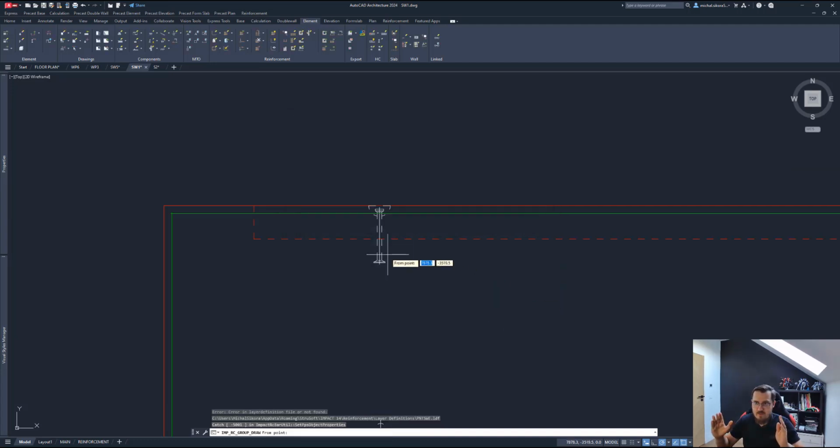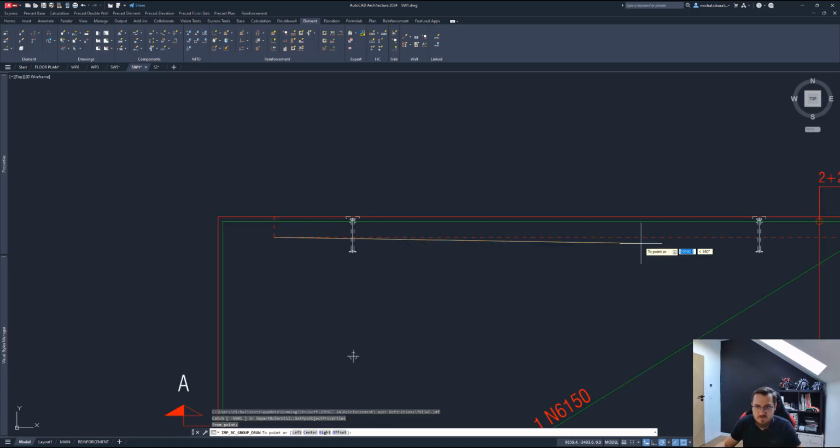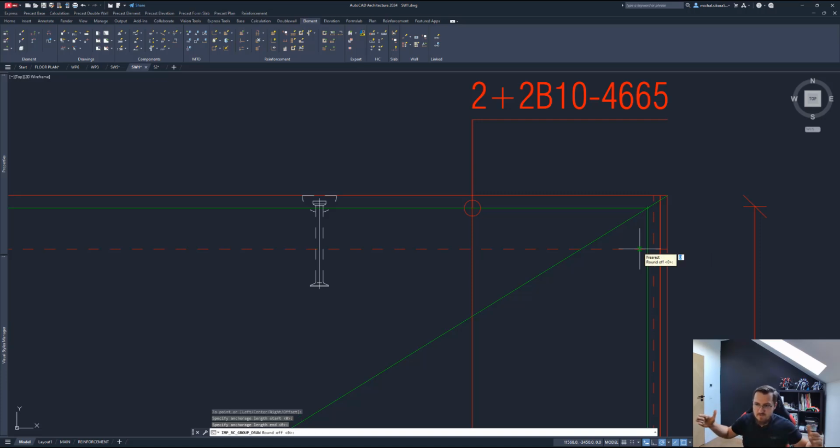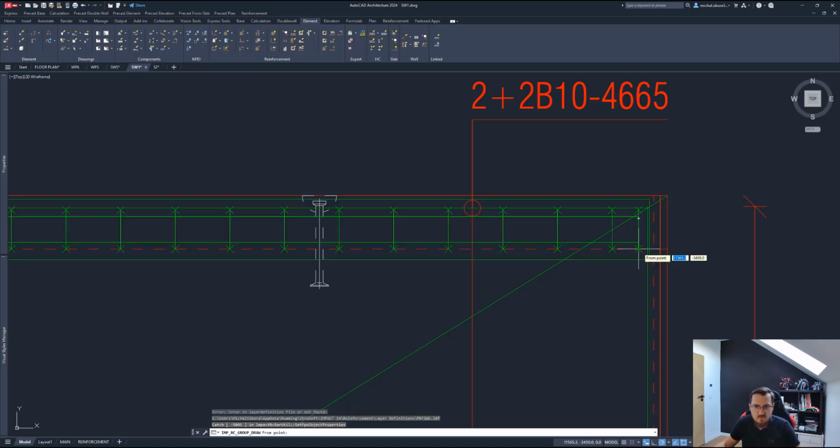So now I have my group properly horizontally spaced in an element. It's just a matter of now placing it properly vertically. So I'll start it from this place to maybe this place, and 0 anchorage, because I could specify the anchorage so straight bars would extend past the start and end point, and I will not round that off.